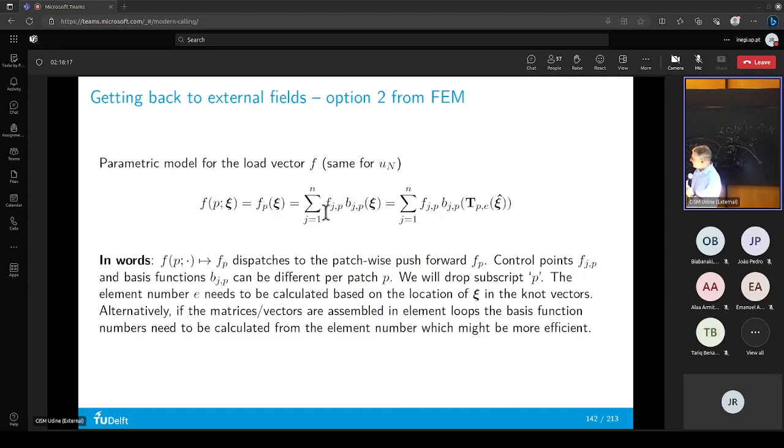The 10th load vector has this basis decomposition. These are the coefficients, these are the bases, and in order to integrate this basis, you push it forward or pull it back, depending on from where you look, on the parent element. So you first declare which of my many functions I have to evaluate, then evaluate it, and for the integration, put in an intermediate mapping.